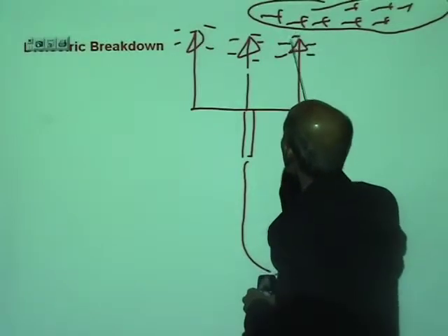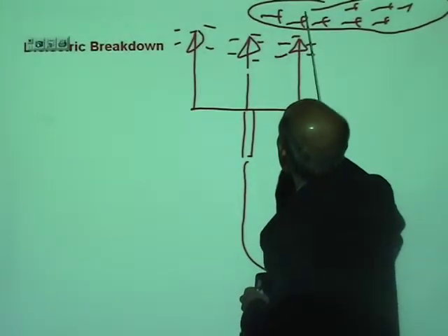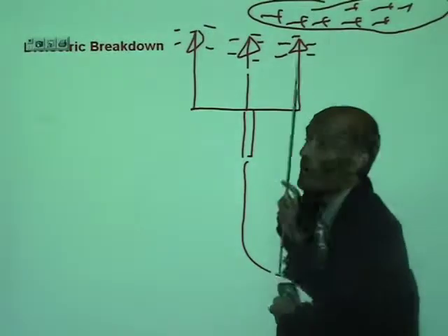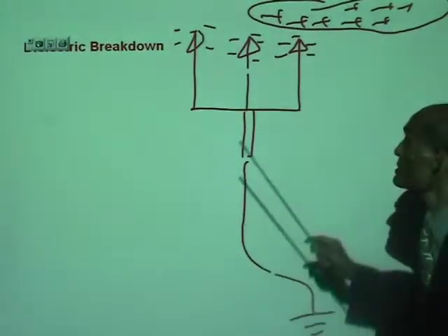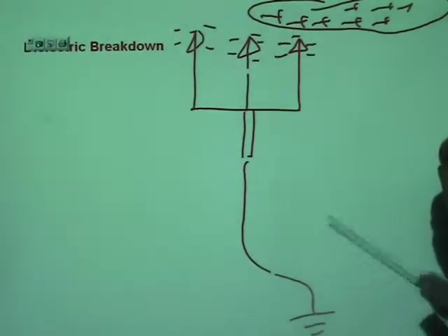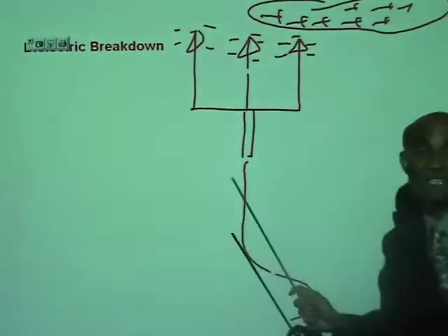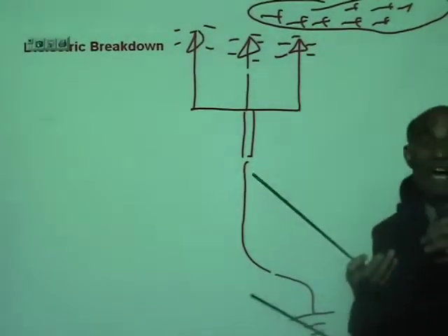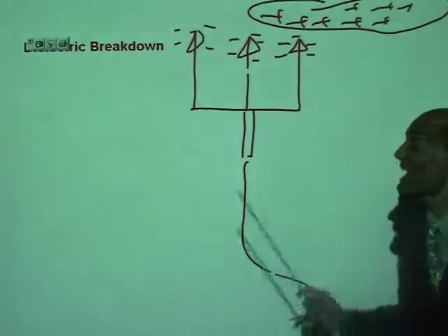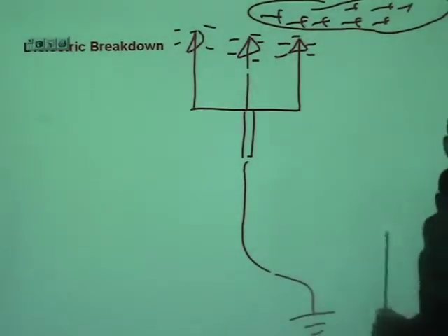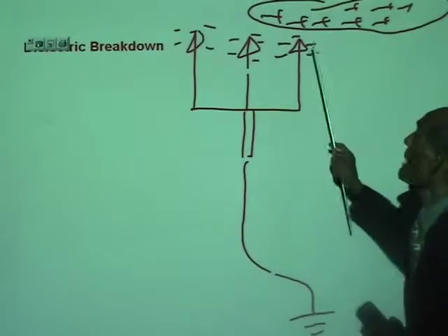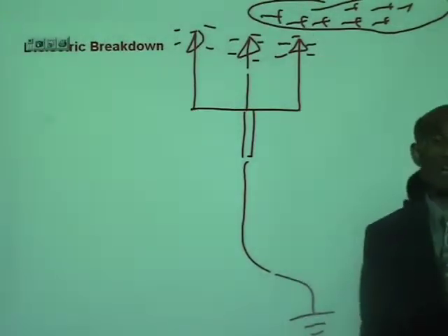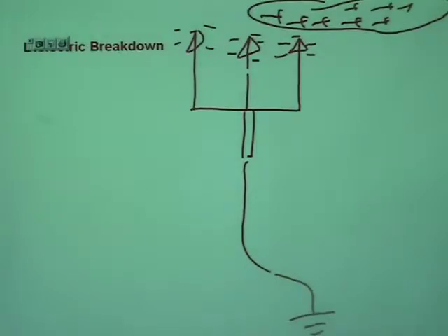And this very high concentration of charges will gradually neutralize the positive charges in the cloud, thereby reducing the prospects of a dielectric breakdown. You remember I told you the prospect of a dielectric breakdown. If the charges accumulate and the potential increases, the dielectric breakdown occurs and lightning and thunder occurs. What happens is the lightning conductors will prevent that by gradually neutralizing all these charges on the cloud. A very useful application of this phenomenon.